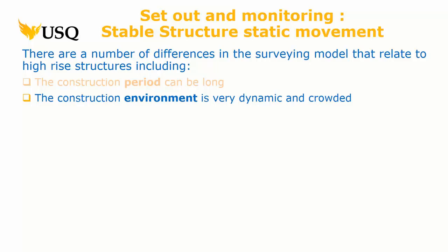As surveyors, what you've got to look at is, how does that impact your survey? Some of that is actually, as we stressed last time, invisible. Refraction. Middle of the city, swirling winds, heat, right? The heat tends to rise vertically up because it doesn't get blown away, as there's not enough open space. And then from a surveying point of view, you start talking about very, very steep vertical angles. Things that are very complex that most surveyors are not used to doing.